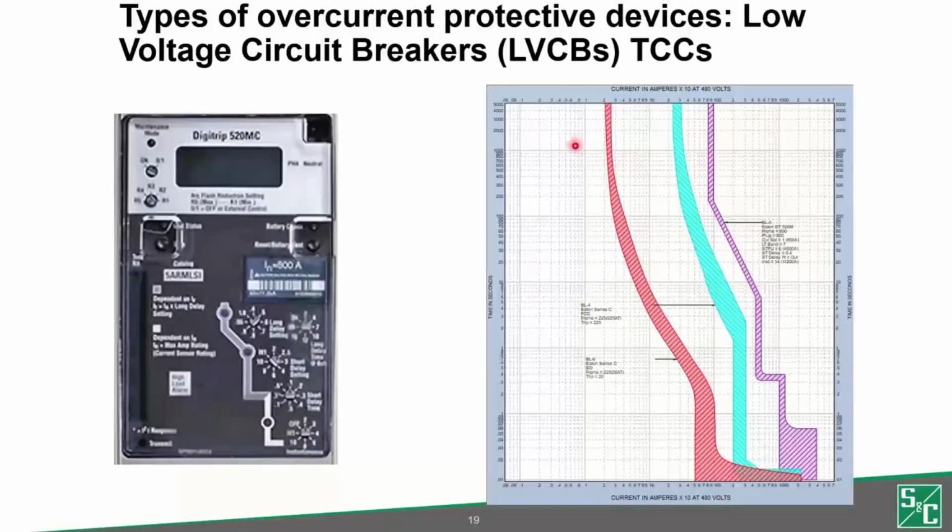The thermal response part of the circuit breakers is a time over current response according to the thermal capability of the bimetal in the breaker. And this area is meant for protecting against overloads, and has a slower response.